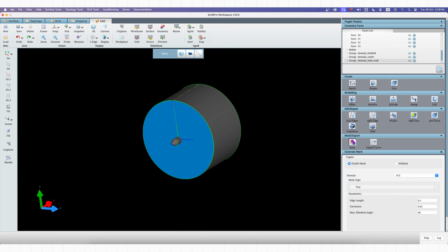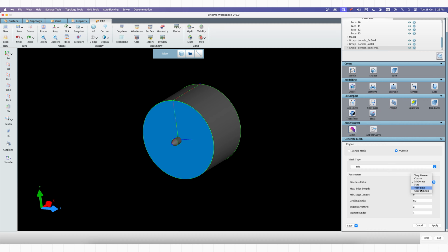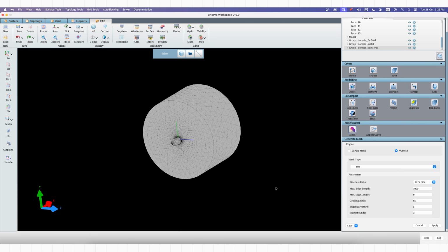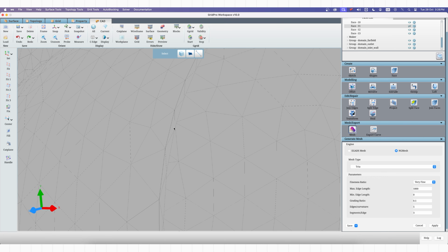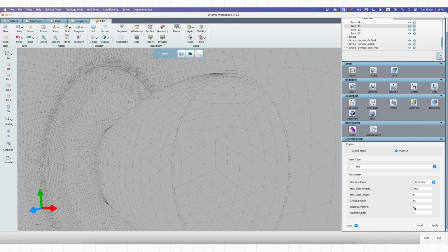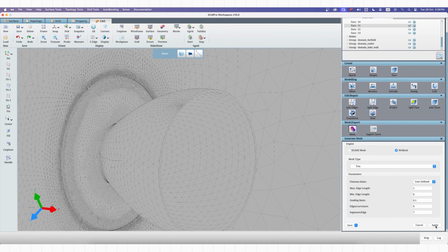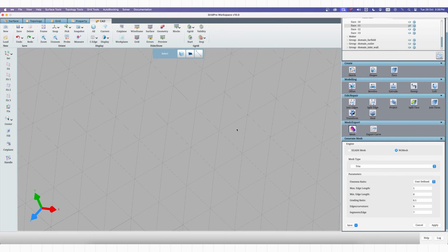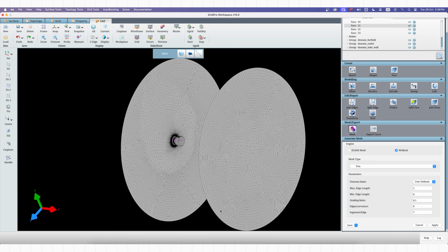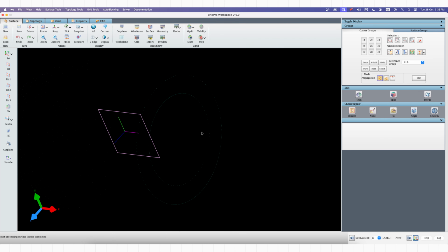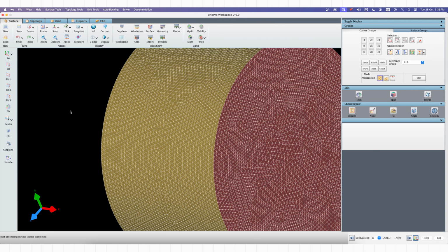After this, let's generate a surface mesh to generate surfaces from the CAD model. Meshing parameters can be adjusted as needed to ensure that all nozzle features are captured accurately. Once the surface mesh is generated, load it group-wise. As you can see, the surfaces are loaded separately based on their assigned labels.